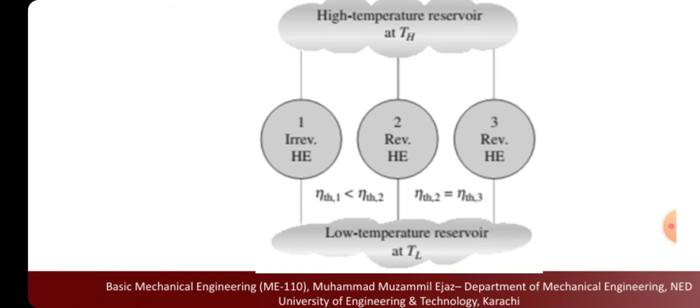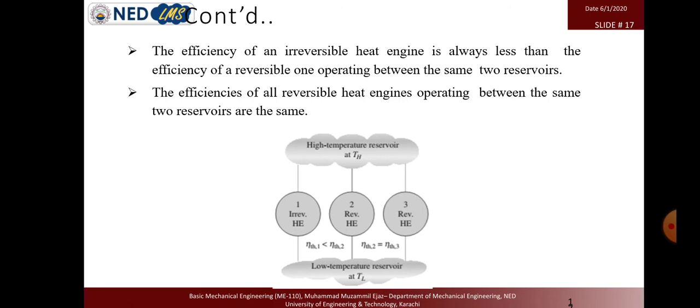All the energy should be utilized in the turbine, but we still don't have a perfect insulator, so some of the energy will be released into the environment. So it is irreversible. We have irreversibilities in the real practical cycle. Due to these facts and losses, the reversible cycle efficiency is always greater than the irreversible cycle.